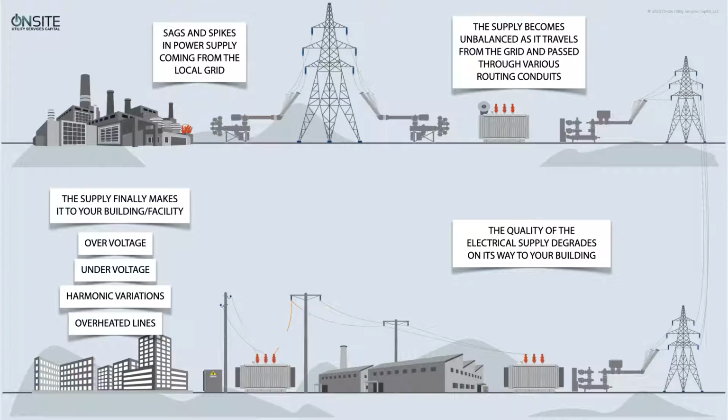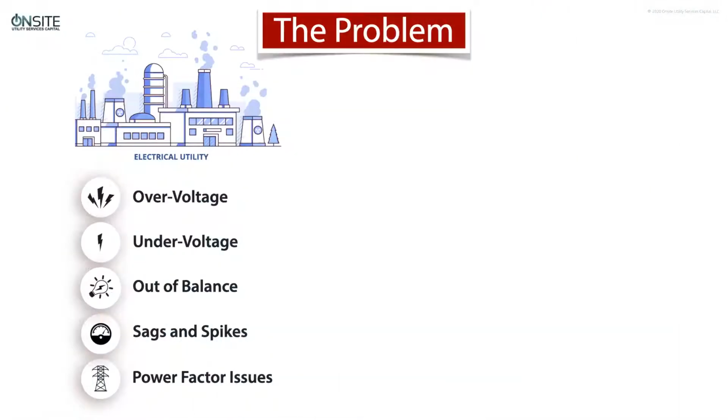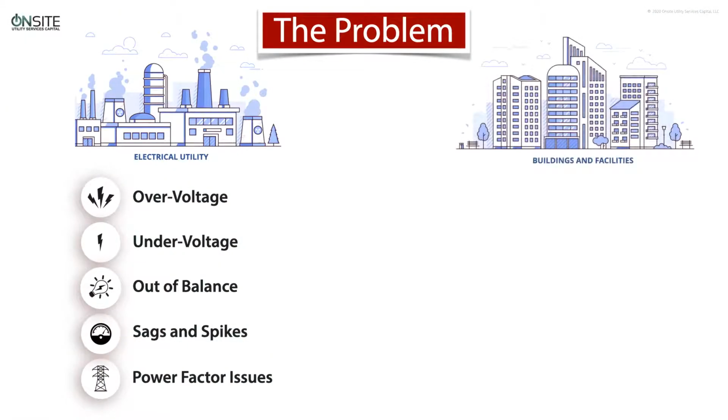Inside your building, motors starting up cause surges, or they can drop off, which instantaneously changes the load the building needs. The harmonics can be distorted, increasing the probability of resonance that can cause overheating of cables and equipment, loss of efficiency in electric machines, electromagnetic interference with communication systems, and more.